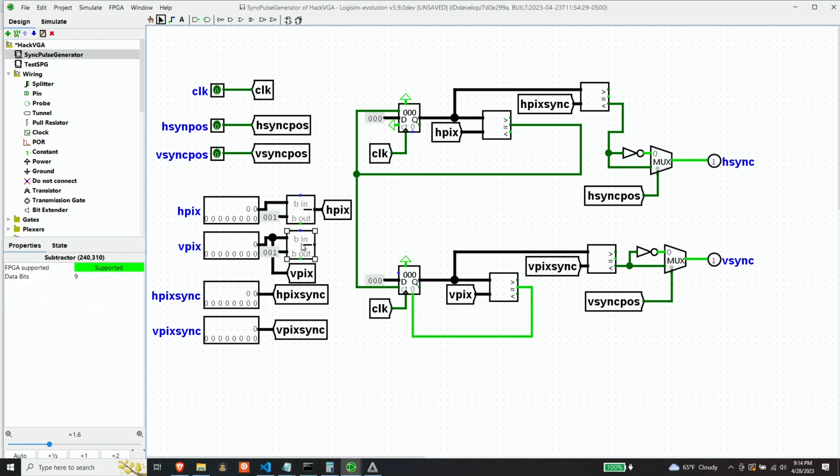So I'm going to go ahead and remove. And those were fairly tricky problems, and of course, the load. It's not going to be loading 0. It's just going to be clearing from this asynchronous clear signal, and this should probably always be ground, because we're never going to load that value anymore. So I'm going to go ahead and put a ground signal here.